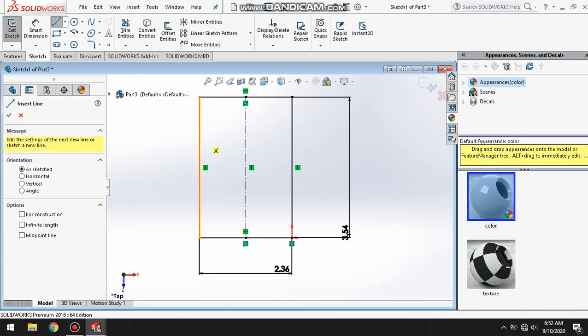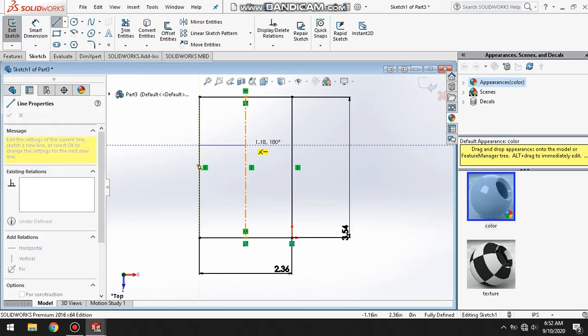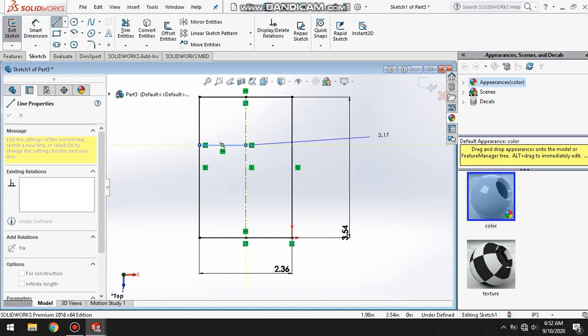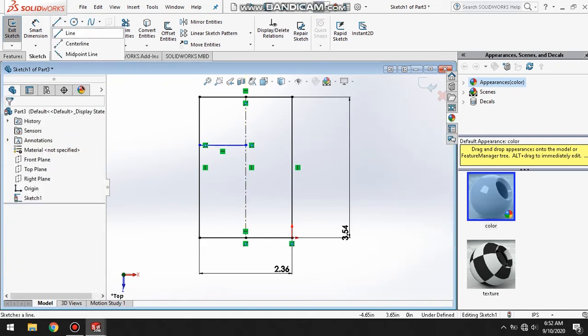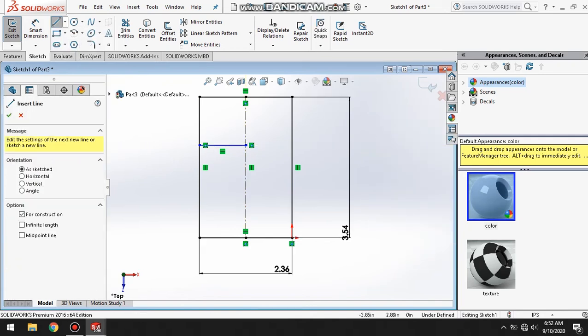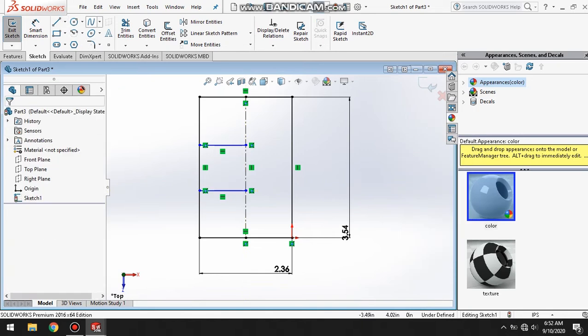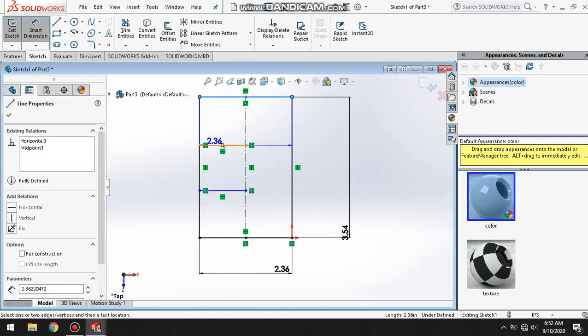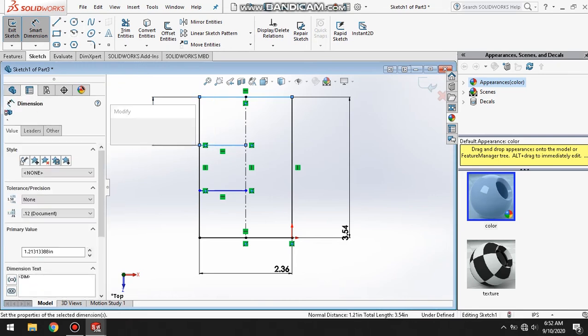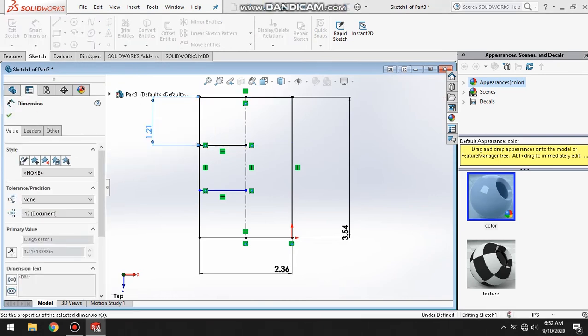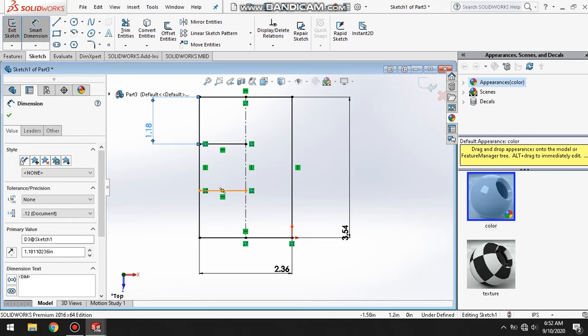Next, select the line to create a horizontal line on the upper left part and lower left part of the polygon. Those lines should be 30 mm apart from the respective parallel side of the rectangle.